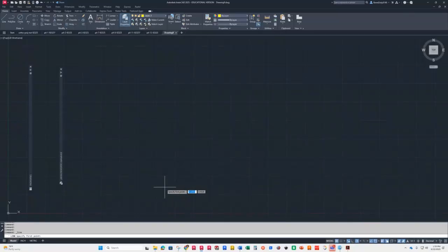Okie doke. So now on this one, if you draw the right side view, I'm telling you not to draw the right side view. I'm telling you to draw the left side view. And you're going to say, why? Well, the reason why is simple. The left side view has less hidden lines than the right side view. It's only one different, but it's still there.